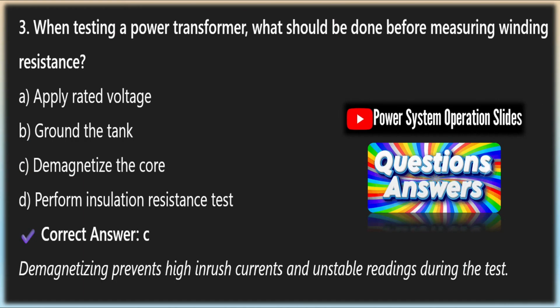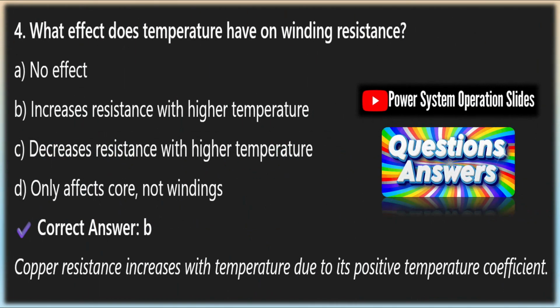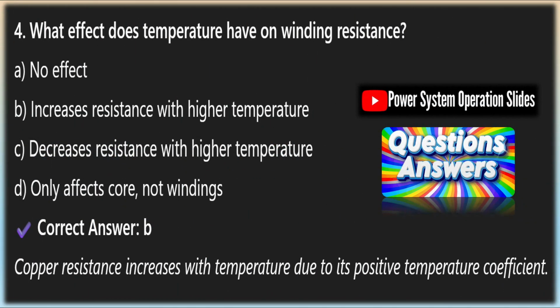Moisture ingress due to high humidity levels can also affect contact resistance at external connections. Maintaining careful control over the testing environment ensures that each measurement reflects the internal health of the transformer rather than external influences. Comprehensive record-keeping of winding resistance values forms the foundation for effective trend-based maintenance programs.